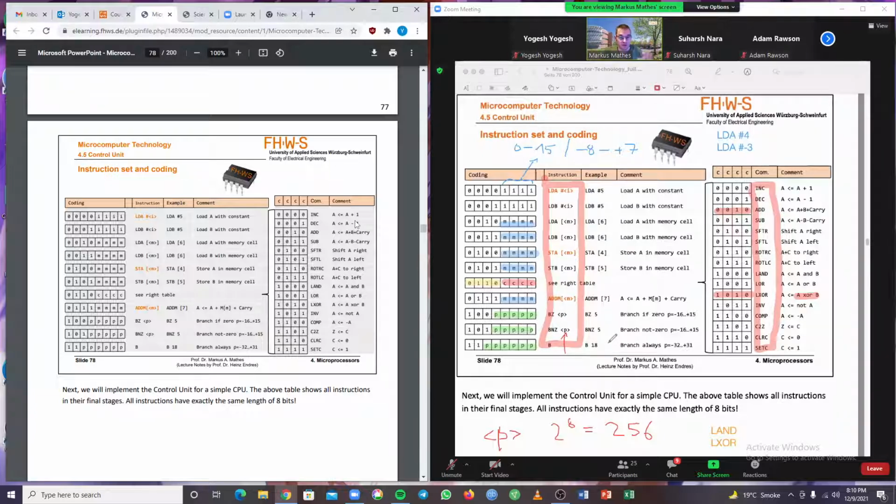So you have literal symbols that you have to write as is. So you have to write LDA, brackets, placeholder, brackets, and in this syntax you can replace angle M with a number. And the allowed numbers are determined by the number of bits. In this case, 2 power 4, 16 combinations, so we can add numbers from 0 to 15.